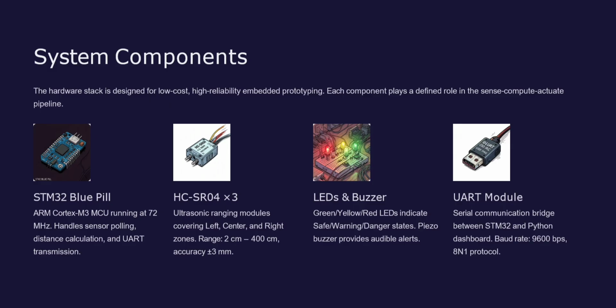The main components used in this project are STM32 Blue Pill microcontroller, 3 ultrasonic sensors, LED, a buzzer, UART communication, and a Python dashboard running on a computer. The STM32 acts as a controller, the ultrasonic sensor measures the obstacle distances, and the Python dashboard displays the sensor data in real time.